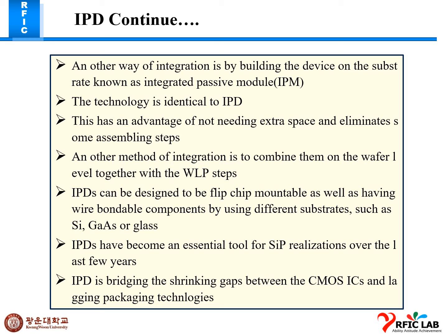IPDs can be designed to be flip chip mountable, as well as having wire bondable components, by using different substrates such as silicon, GaAs, and glass. IPDs have become an essential tool for system in package or SIP realization over the last few years. IPD is bridging the shrinking gap between the CMOS ICs and the lagging package technologies.